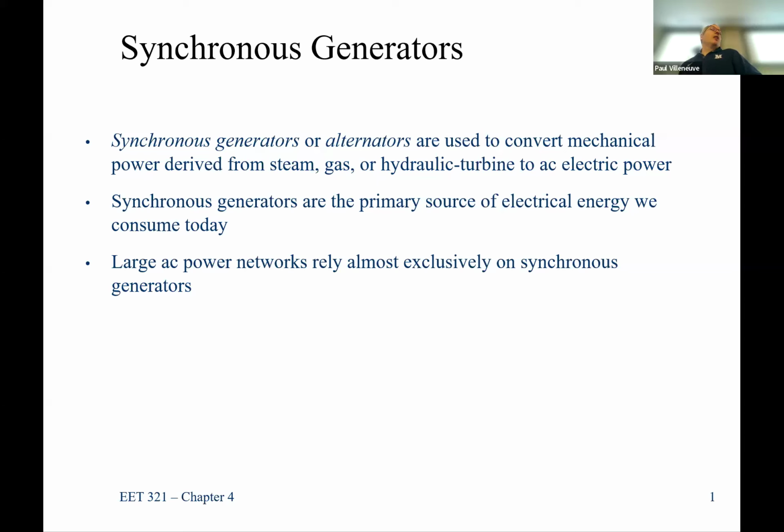It used to be almost all of it, not that long ago, but because of inverter-based generation, and wind farms mostly use what are called doubly fed induction generators, which we'll learn about with induction machines in our next chapter. But the concept of a synchronous machine is that it works so well to support the grid, and you have this one additional control element that gives you so much flexibility and control